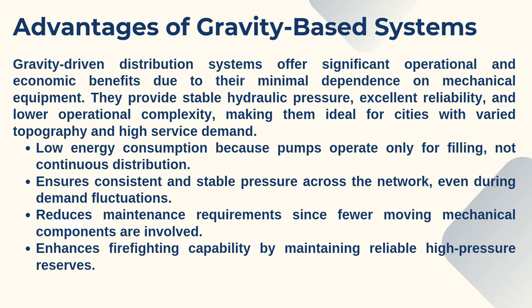Alright, next is about the advantages of gravity-based systems. Gravity-driven distribution systems offer significant operational and economic benefits due to their minimal dependence on mechanical equipment. They provide stable hydraulic pressure, excellent reliability, and lower operational complexity, making them ideal for cities with varied topography and high service demand, including low energy consumption because the pumps operate only for filling, not continuous distribution, and also ensure consistent and stable pressure across the network, even during demand fluctuation.